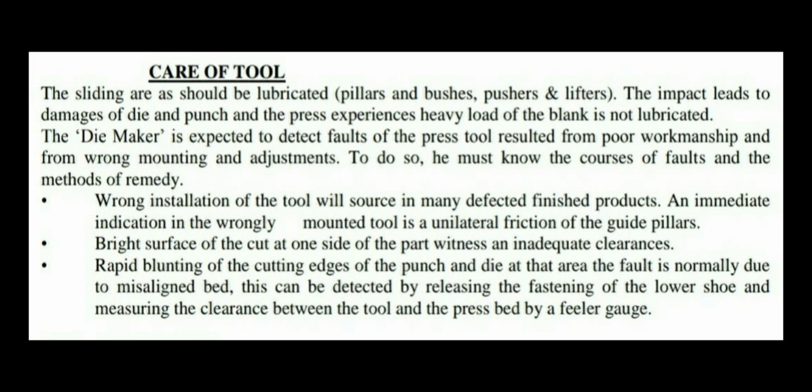The sliding areas should be lubricated, pillars and bushes. The impact leads to damage of die and punch, and the press experiences heavy load if the blank is not lubricated.